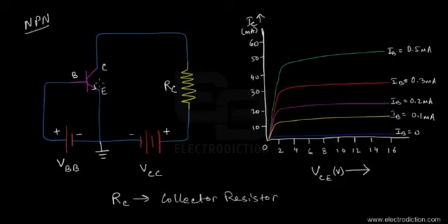Considering that this BJT would operate in the active region, and that its input junction, the emitter junction, has been forward biased, the most obvious thing we would come across in its output loop is a collector current that would flow due to a corresponding input base current entering the BJT through the base terminal.